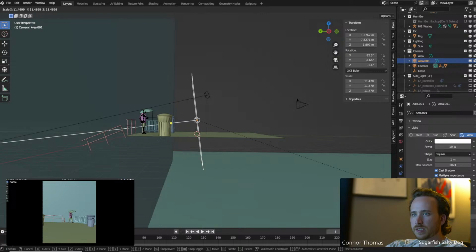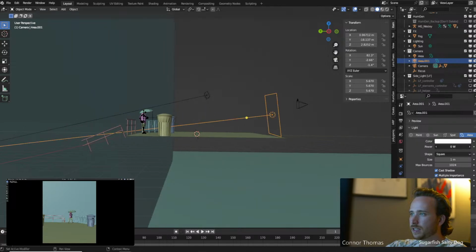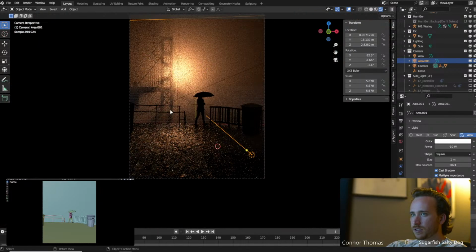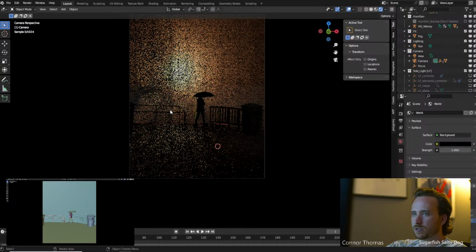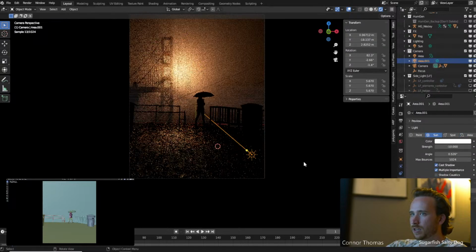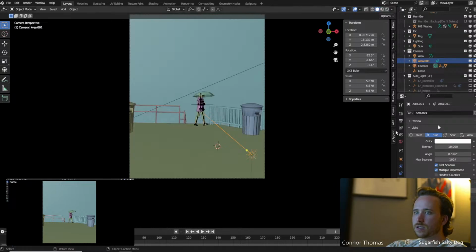Okay, I'm gonna scale this guy up. Basically, from this end here, we have to have a negative number. If you have a negative number, it actually sucks light out in Blender versus adding it. So delete that. Actually, I almost think if we added a sun, it's going to do almost what we want.